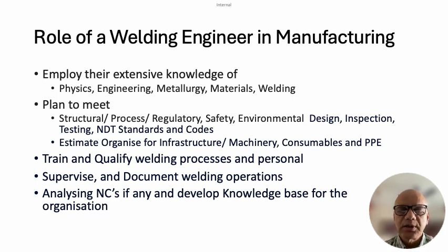This will tell us the grain size, the corrosion properties, the impact properties, the sluggishness of this material, the fluidity of this material, and whether it can be worked in different positions. And then comes formability, and then machinability, and then welding, whether this alloy can be easily welded, or what are the best options to weld this.